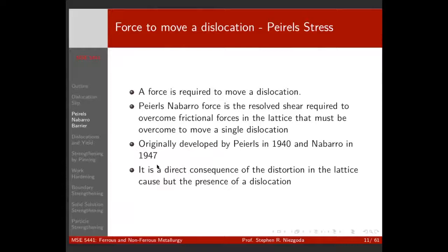I would hope you'd think that by asking the question, I'm leading you to the answer of yes, right? But why aren't ceramics ductile? Diamond has dislocations in it, right? Why isn't diamond ductile? So dislocations aren't mobile. Why aren't they mobile? What's different between diamond or rock salt or metal? The bonds, right? So in diamond we have covalent bonds, not easy to break, right?